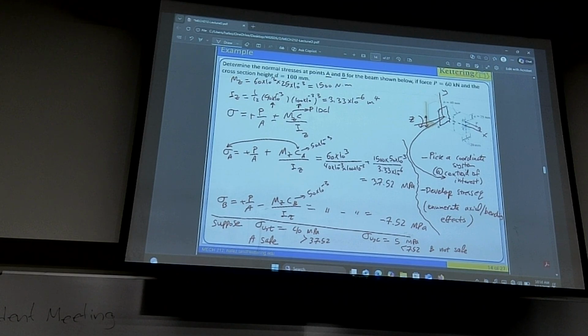So that means if you still want to use that hitch, for instance, Nathan gave us that example, then you have to work on the bottom point, because point B is not safe. You have to strengthen that point B, or minimize this distance, so that it creates less moment, therefore eventually less stress. That's a design thing. You should get that.